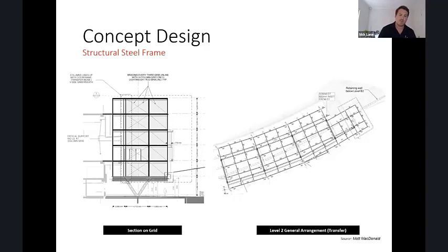So essentially what we had is we've got vertical supports back to the existing structure at about 11-metre spacings. And our structure in between didn't span that far at every level. So what we've got is a large transfer, I guess, grillage structure, you could call it, at level 2, which you can see is on the image on the right. And then the individual bays in between is essentially the room layouts above. So we could frame up internally between those in each internal room wall with steel framing and steel floor joists between. Next slide, please.